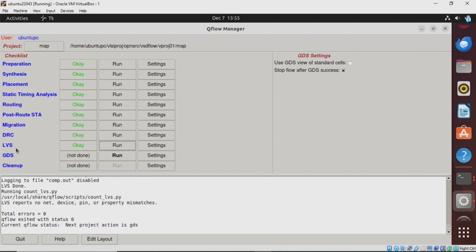The Verilog file is used to generate the schematic netlist using the tool called Netgen, and the layout netlist is generated from the GDS file from the physical synthesis tool. Both are compared. If all the nets are matched, then the LVS will be clean.